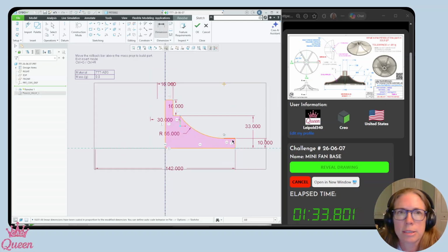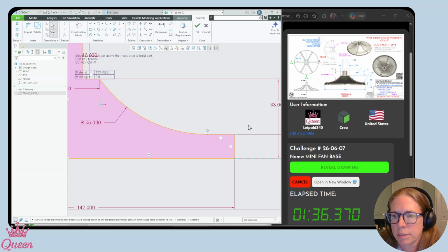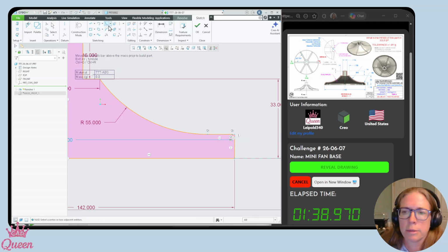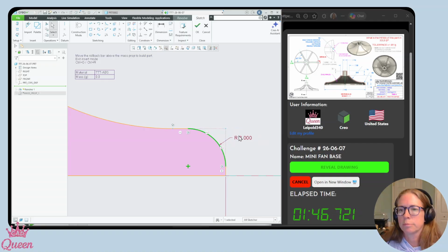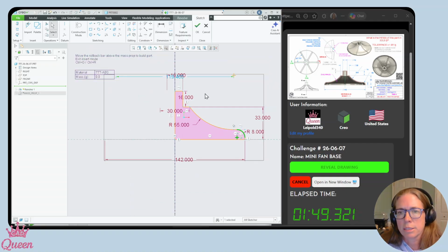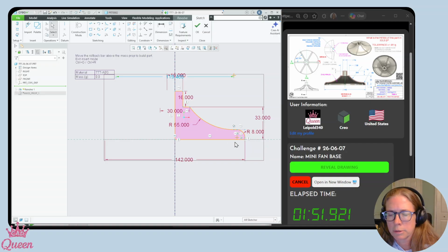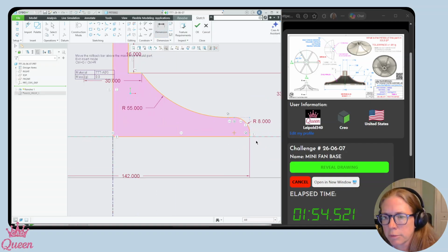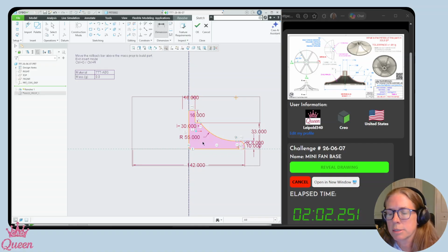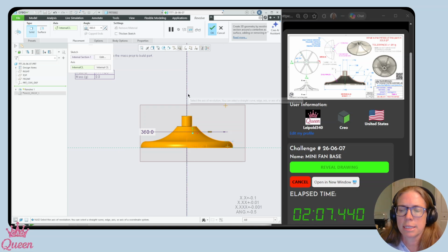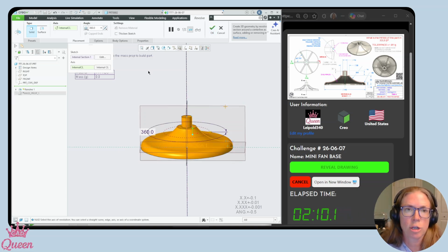So the only thing we're missing is this arc down here, or this fillet. Let's just drop it right in. Okay. And let's give that a radius of 8. Okay. So when you create the sketch inside the revolve, oh, we lost our height there. That's unfortunate. We'll get it back. Okay. It automatically gives you these diameter dimensions, and I don't have to specify the axis of revolution as long as that's your first sketch or first thing you draw. All right.